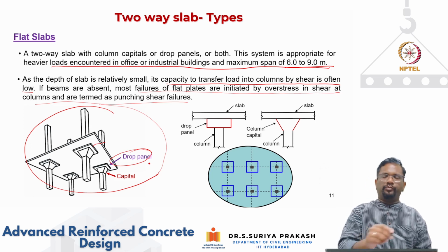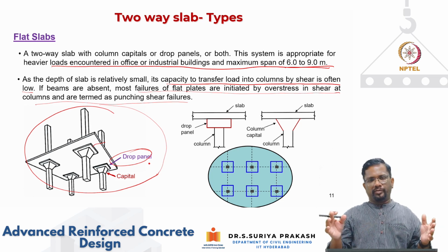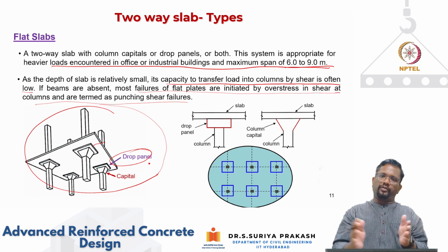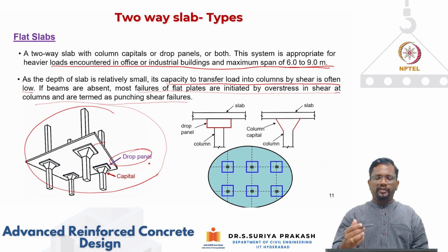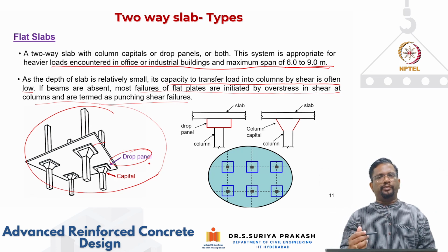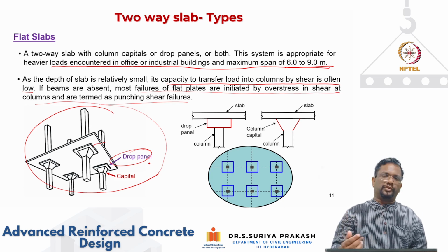And if you do not have post tensioning, you lose the effect of pre-stressing, and then your spans will be limited, and the load you're going to transfer is also going to be limited. That is the reason flat plates and flat slabs are usually done with post tensioning.